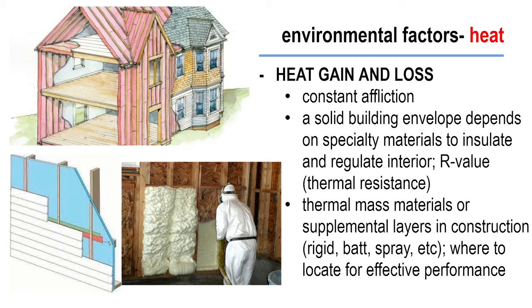So having a solid and really tight building envelope is the best solution for overall energy use reduction in a building. And you do that with your insulation as well. You'd pick your insulation based on its R value, which is just its thermal resistance. So how well can it battle that need for equilibrium, of that hot air outside wanting to make the inside air the exact same temperature that it is.